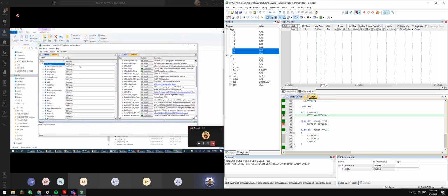So that's the reason I prefer Keil uVision, but based on the statistics, Microchip does very well in marketing. And Microchip is free if you don't need the optimization. However, this one is not free. It limits the code size. For example, for MCS51 they limit it to 2K. If exceeded 2K, it will not function well. But 2K for students is perfectly all right. I think it's 4K for ARM microcontrollers.